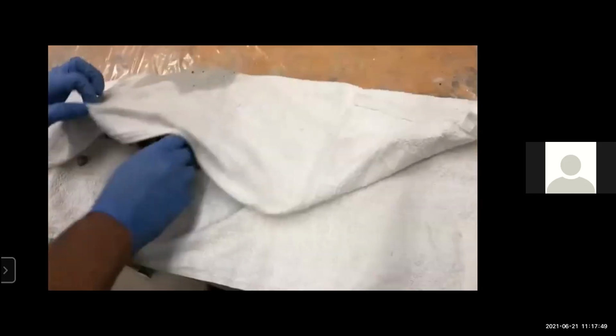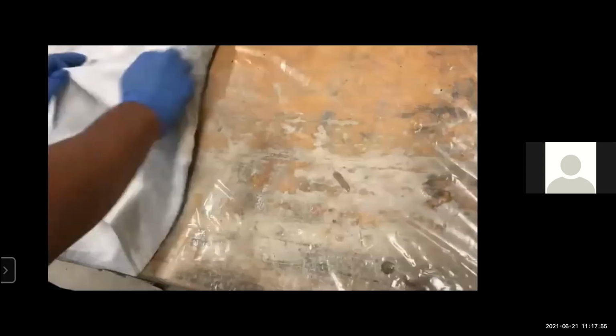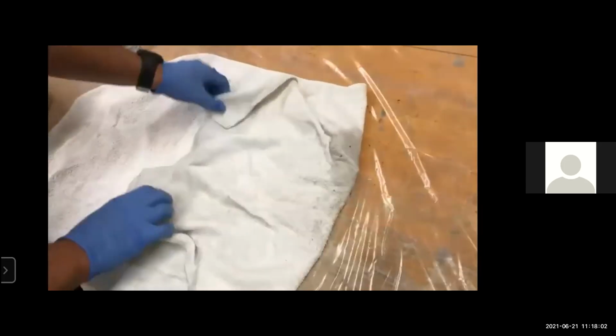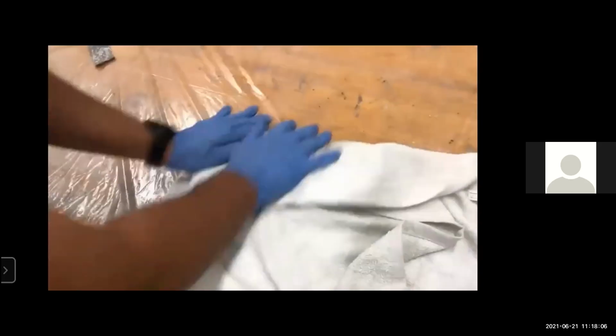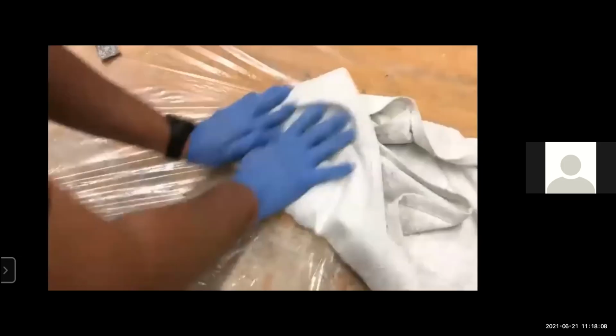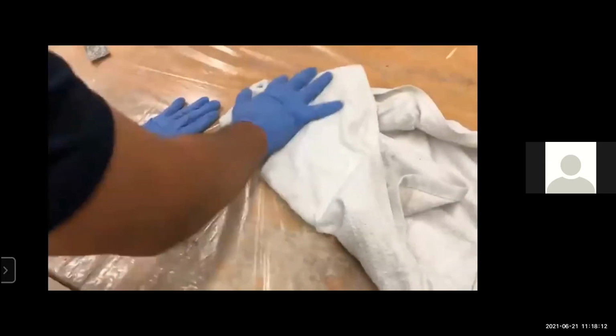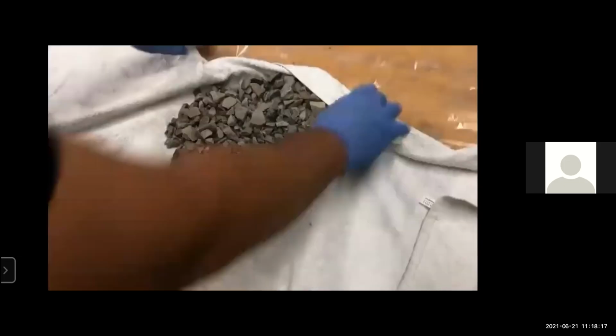We take a dry towel and put all the aggregates, then rub these aggregates with the cloth. The size of this cloth is 75 into 45 mm. Two cloths will be taken for rubbing these aggregates and drying them. From all the sides, we clean and dry all the aggregates.